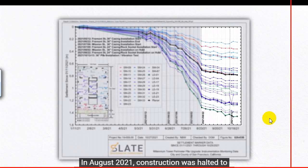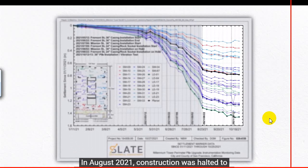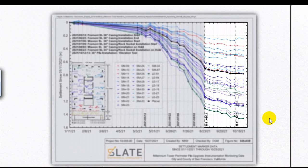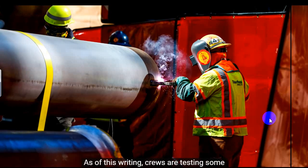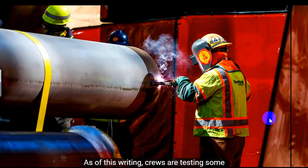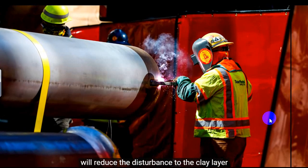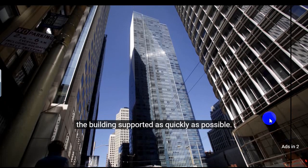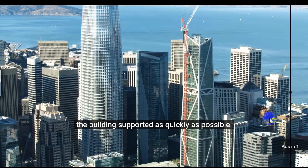In August 2021, construction was halted to reassess the plan and find a solution to install the foundation retrofit safely. As of this writing, crews are testing some revised drilling procedures that they hope will reduce the disturbance to the clay layer so they can get those piers installed and the building supported as quickly as possible.